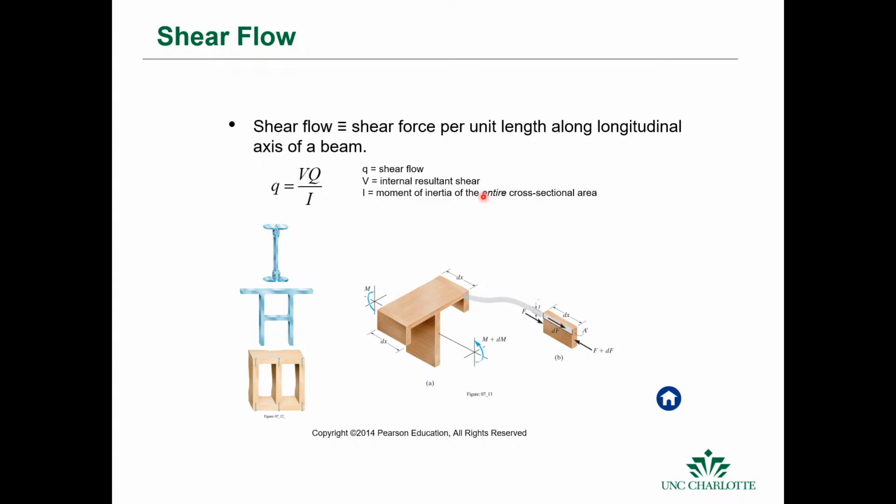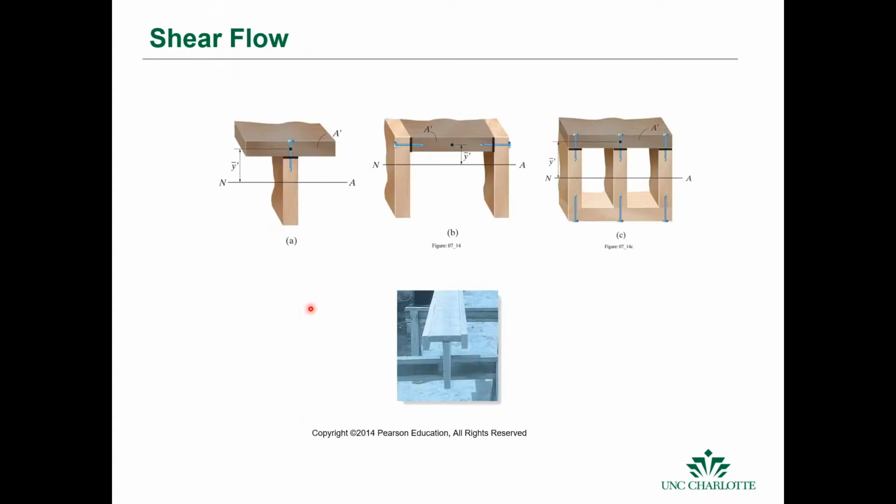And that shear is important if you're using different types of fasteners. You can calculate that as well, and it's important when you're making beams or composite beams or structures or bolted structures, because you are going to have this shear stress that's going to act on these planes where you have either bolted joints or potentially welded joints or nailed joints. In this case we have nails.